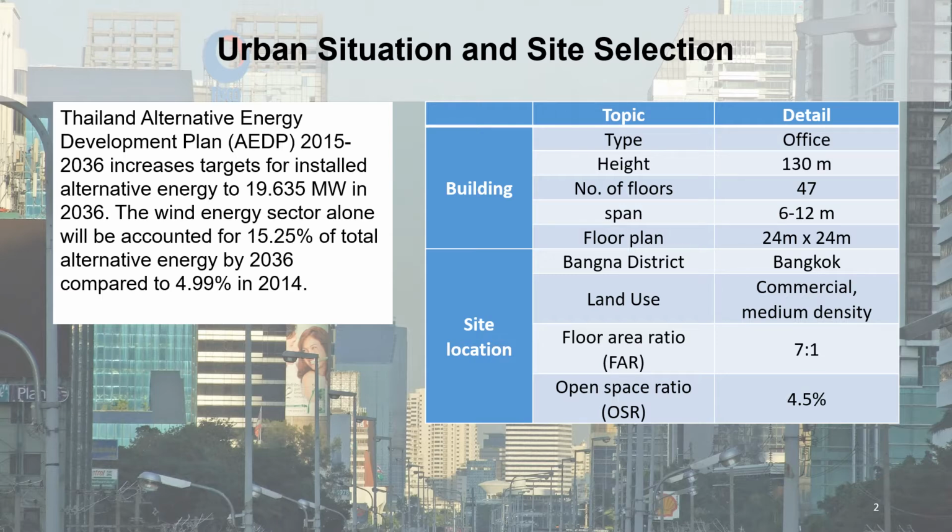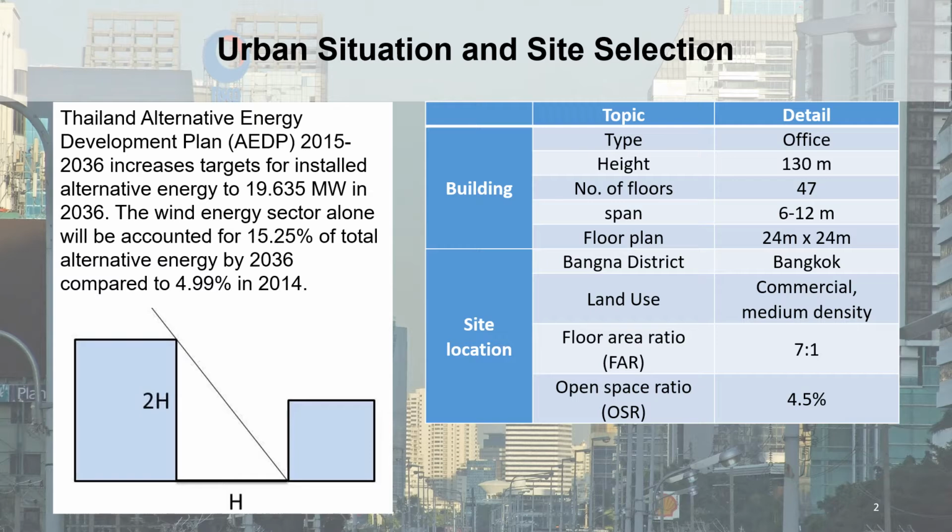According to Thai building regulations, building height from any point shall not be more than twice the horizontal distance from such point, which is perpendicular to the boundary of the opposite side of the nearest public road. Therefore, the total building height for the study must not exceed 130 meters, as calculated from the 30-meter wide road and height restriction in Bang Na zone.